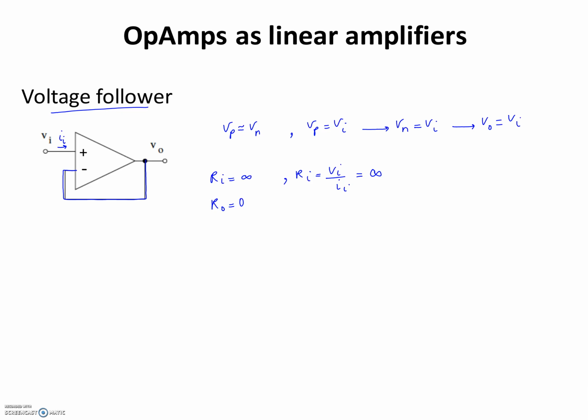The input signal is connected to the positive terminal input, and the negative feedback is present. In this configuration, input impedance is high, output impedance is low, and generally they are used as buffers in situations like when you have a source with high output impedance and a load with low impedance. Because their impedances don't match, you can use a buffer in between. You can use a buffer to connect that source to the low impedance load without suffering the impedance mismatch between source and load.